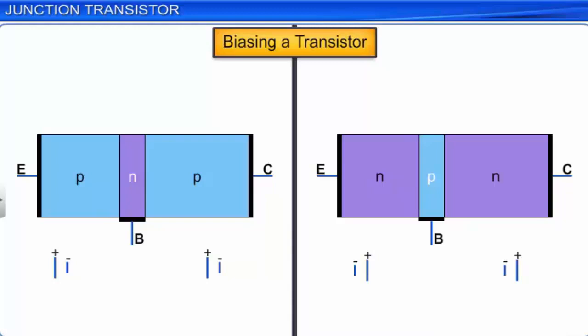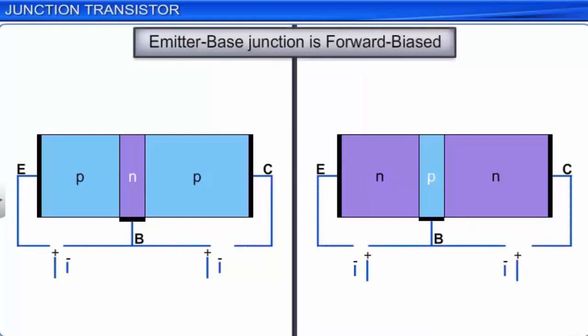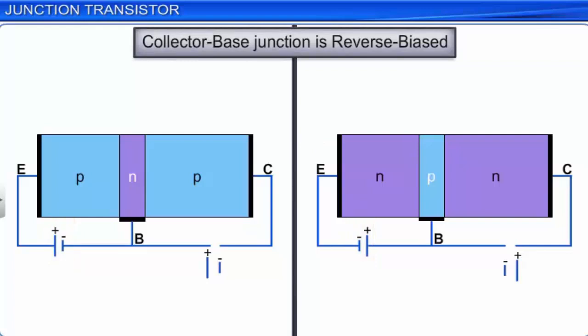In this module, we discuss transistors in common base configuration. During biasing, normally the p-n junction between the emitter and the base is forward biased, while the p-n junction between the base and the collector is reverse biased. The reasons for adopting such a biasing scheme for the two junctions will be discussed at the appropriate juncture in the course. A transistor with its emitter-base junction forward biased and base-collector junction reverse biased is said to be in an active state.